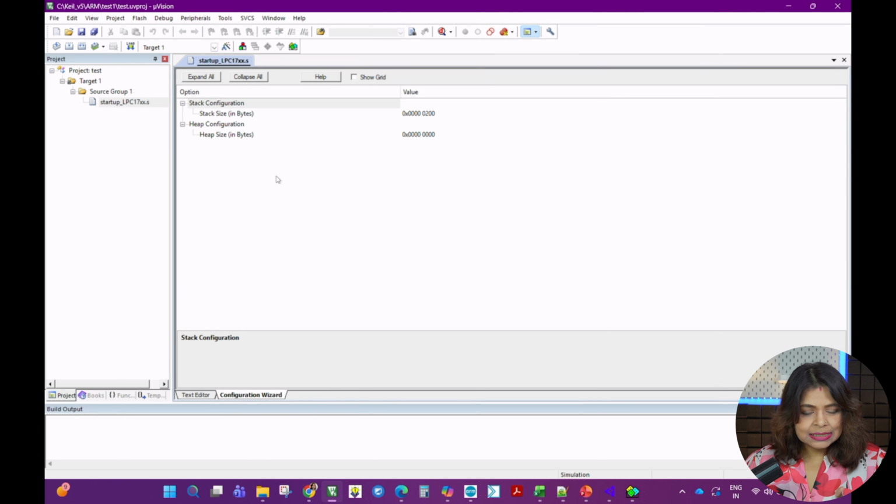So now we spoke about this .s. Now we have to talk about .c. What is the system initialization file? Why is it required? Crucial. Well, these two files may not be compulsorily required for all devices. Again, it comes down to what device you have selected for your embedded system and which specific Cortex-M MCU you are planning to program. But if you are planning for Cortex-M, be it the lower-end Cortex-M0 or the higher-end M55, M85, these two files, the startup code which is .s and the system initialization file, are both mandatory.